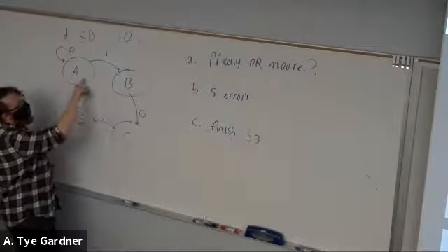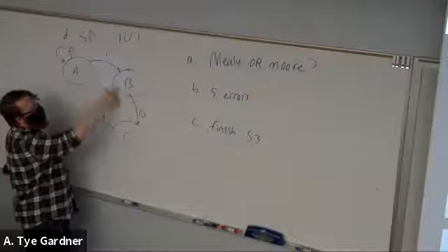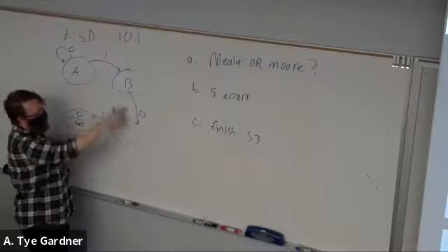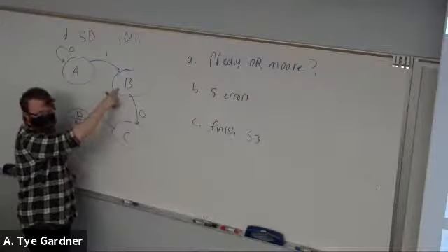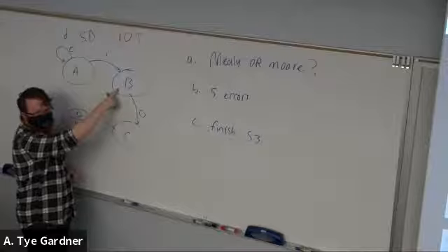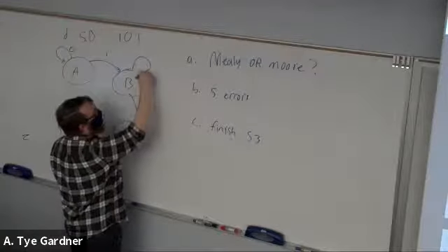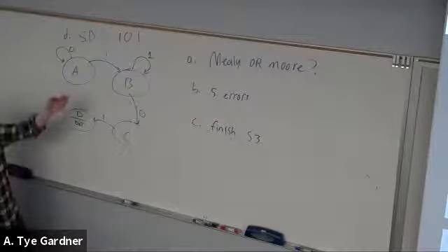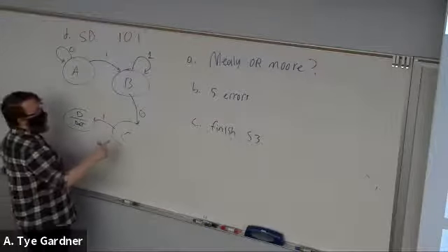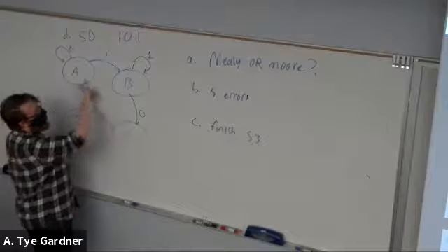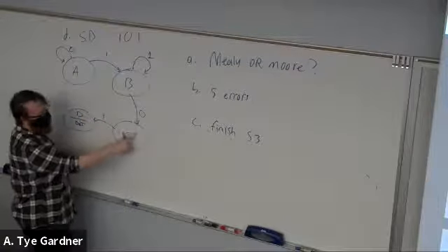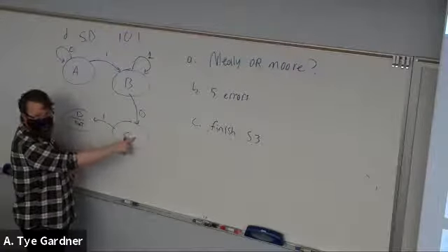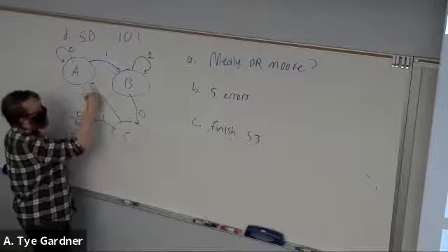Now, B is a little bit trickier and people mess this up. So if I do 1 and then I see another, if I see the 0, I go on. What happens if I see the 1 in B? We stay, because B is saying I've seen 1, 1. 1, 1, 1, 1, I hang out in B. All right, C says if I get 1, 0, 0, where do I go? Yes, I restart.